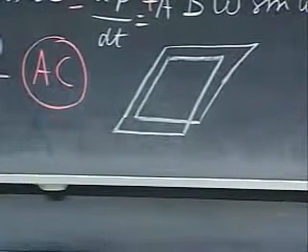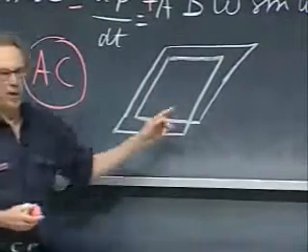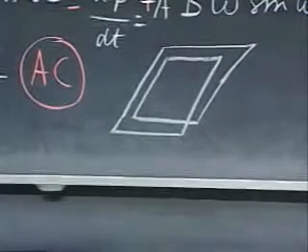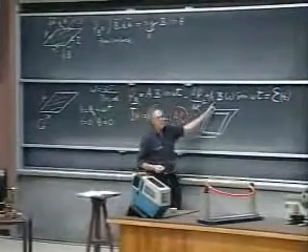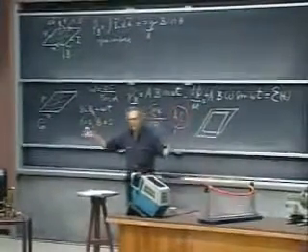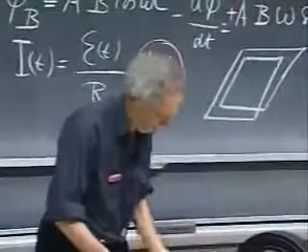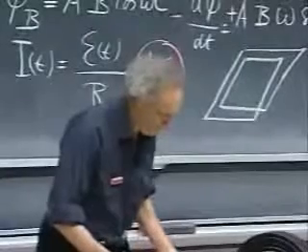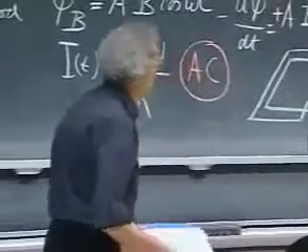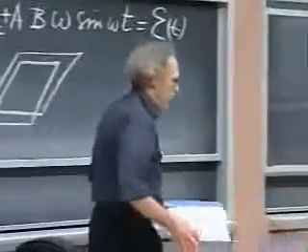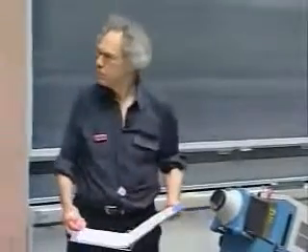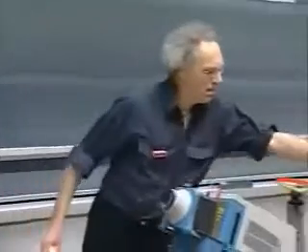And if you have n windings in one closed loop, capital N, then the EMF that you get would be n times larger. And you can make n 1,000. There's no problem with that. I'm going to do a demonstration for you whereby I'm going to use the Earth's magnetic field and a loop that you see here that has 42 windings.